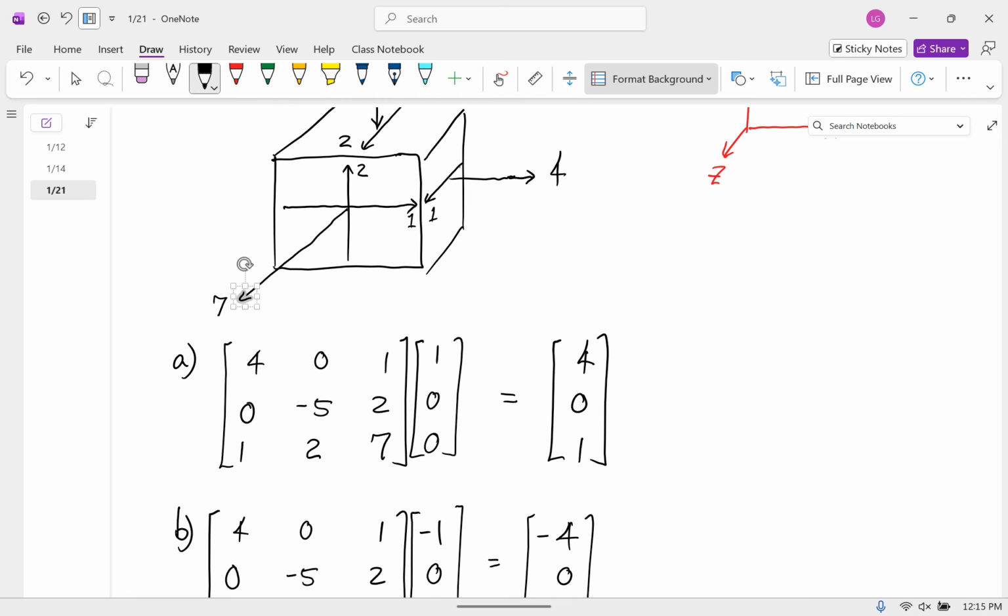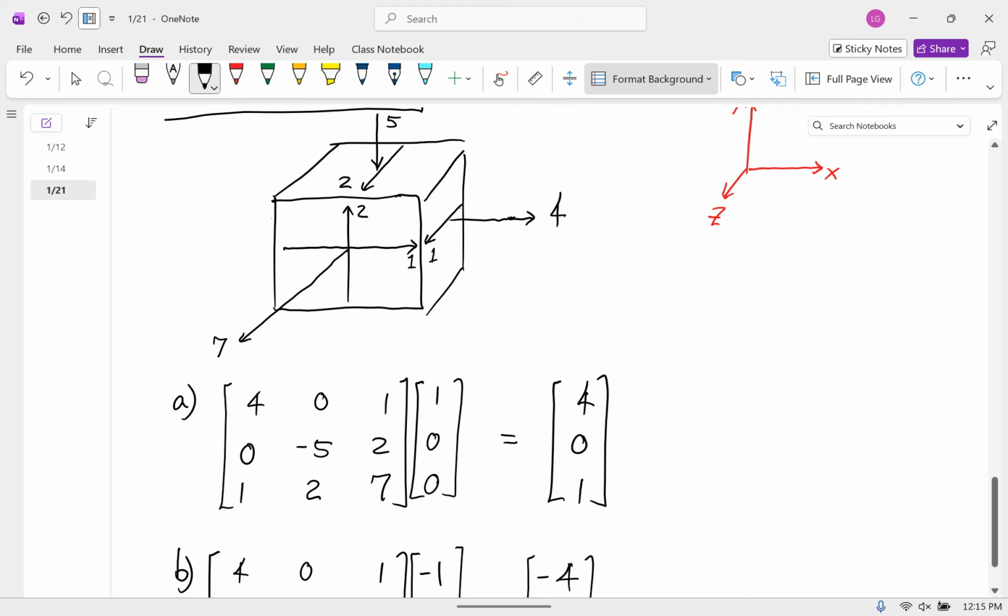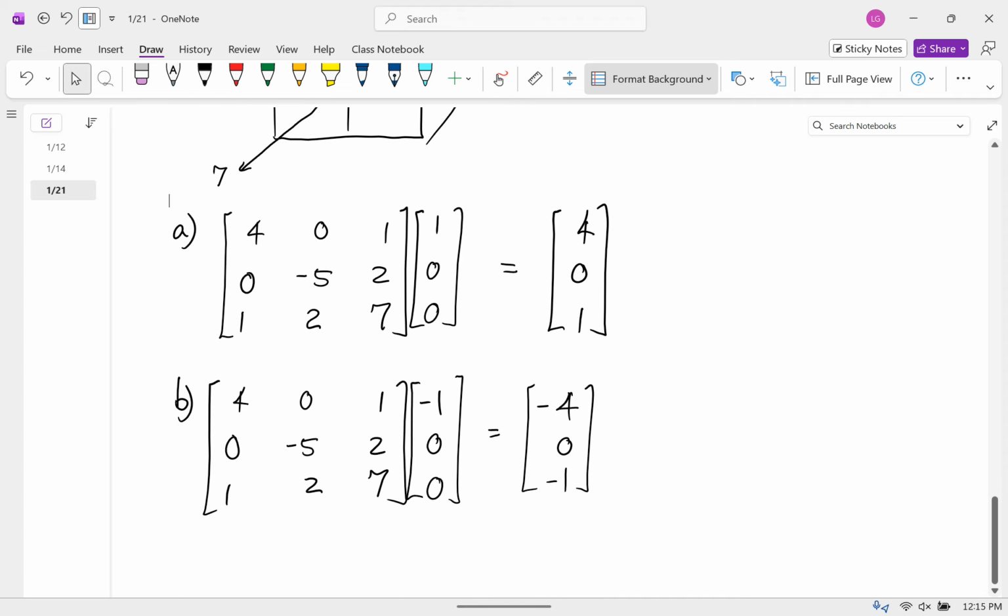Remember that when we were going through that rough derivation of what all the stress tensor values were, we said that in order to be in static equilibrium, in force equilibrium, we always had to have those elements be equal and opposite on opposite faces. So since that negative x face is equal and opposite to this, those components just need to be opposite signs. And so, yeah, that's the traction on that negative x face.